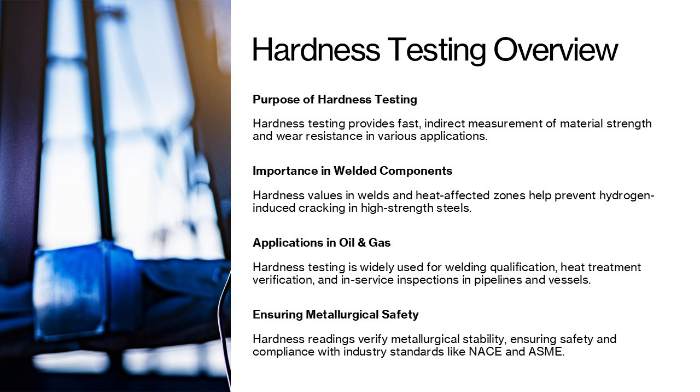Hardness correlates with yield strength, tensile strength, and resistance to wear or indentation. In welded components, hardness values are particularly important because excessively high hardness in the weld or heat-affected zone can lead to hydrogen-induced cracking, a common failure mechanism in sour service and high-strength steels.